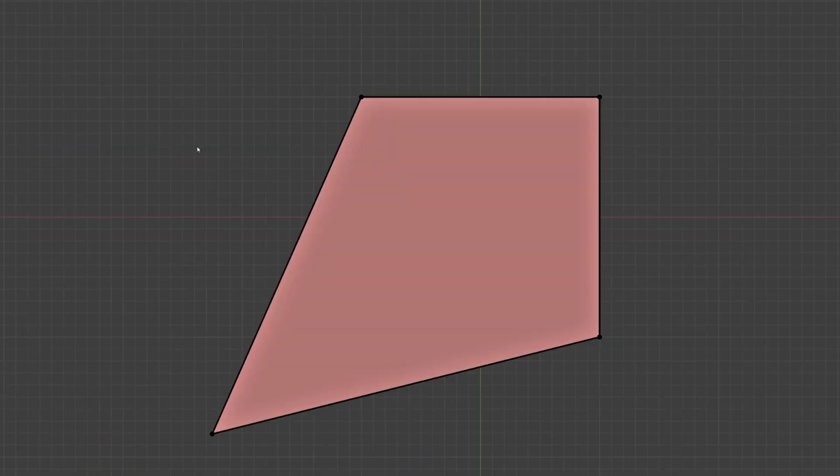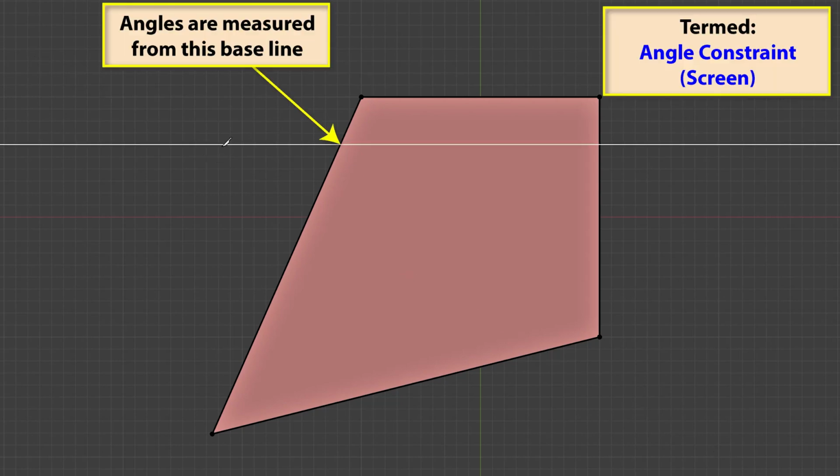Another straight line cut option is achieved by pressing the A key. Since the choices available here get a little complicated, we'll demonstrate on a simple plane where one vertex has been moved to create a kite-shaped mesh. Once we've initiated the knife cut by pressing the left mouse button, pressing A creates a white line showing the direction in which the next cut will be made.